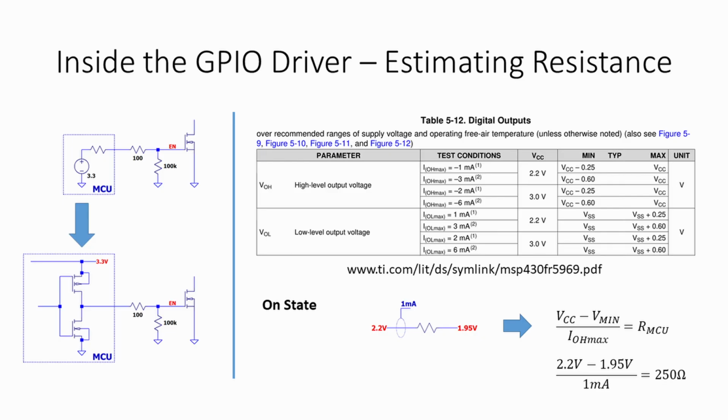So while the high Z state that we just discussed shows you why using a weak or high resistance pull-down is a bad idea, this output resistance bounds the other side of the pull-down. If for whatever reason you chose to use a 500 ohm resistor for a pull-down, it should be clear that with a 250 ohm output resistance, the 3.3 volt at the rail will be reduced significantly by the time it gets to the gate of the FET due to the voltage divider that forms.